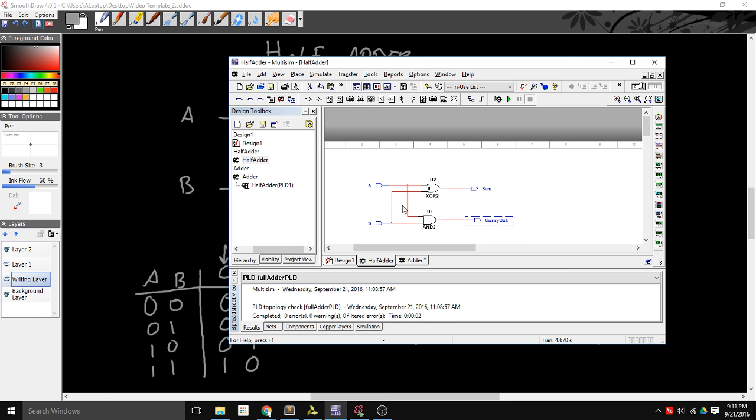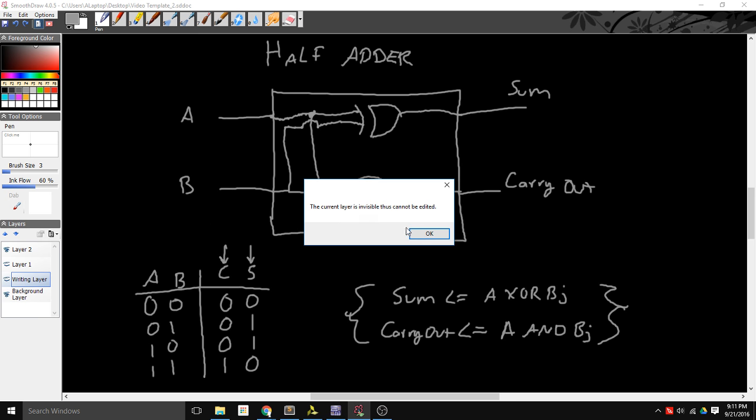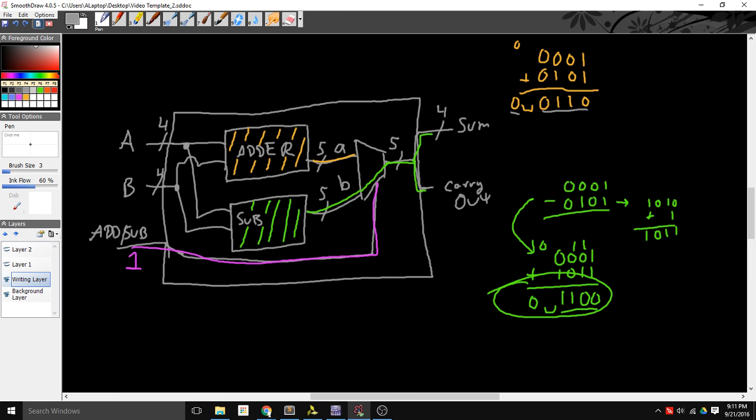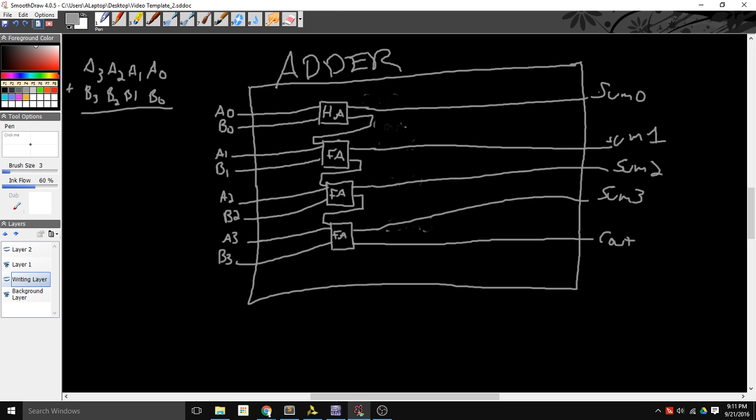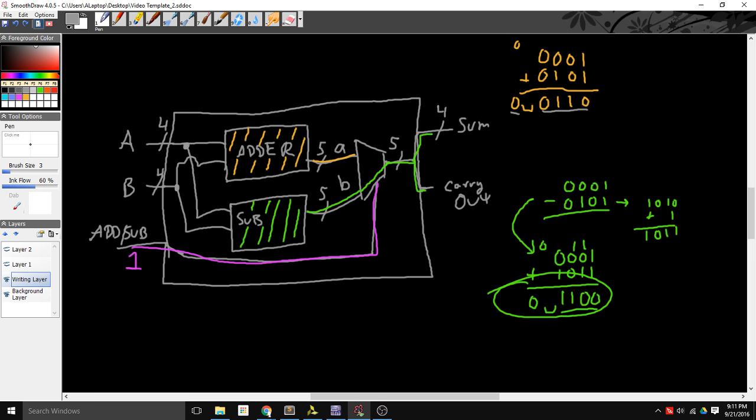And sometimes I don't usually use Multisim, but I like to sketch out the general layout of my designs. So I have my top level schematic of the entire system, and then I draw the components that are living within that top level, and then depending on how complicated each of those components are, I'll break those into smaller and smaller components until I get to the lowest level I can implement in VHDL, and then I build up the total system from there.